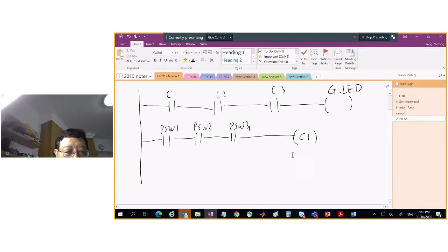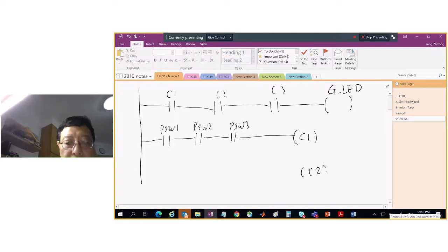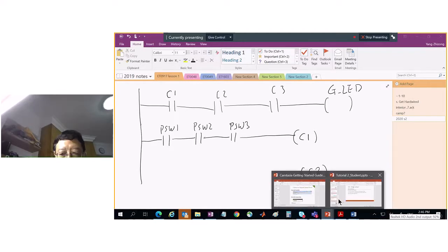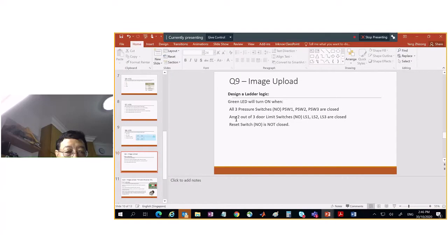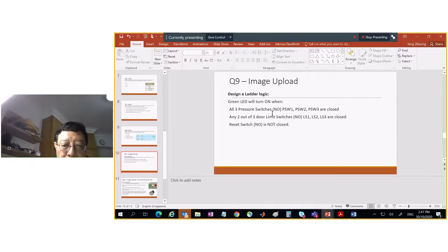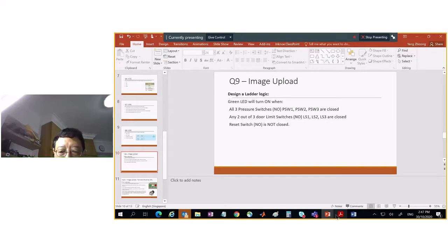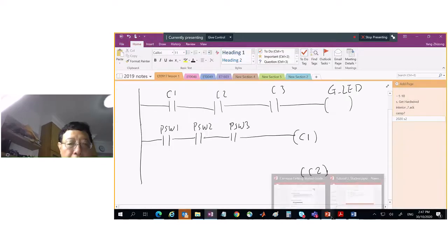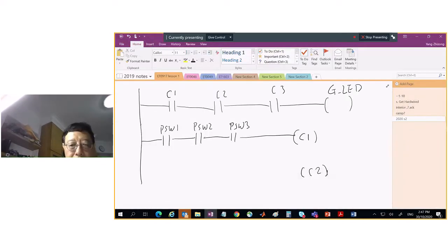Right? Then I program the second condition. The second condition is my C2. According to the original requirement, condition 2 is only 2 out of 3 door switches. There are three switches, LS1, LS2, LS3. When only 2 of them are closed, then this condition is met. So what I can do is...